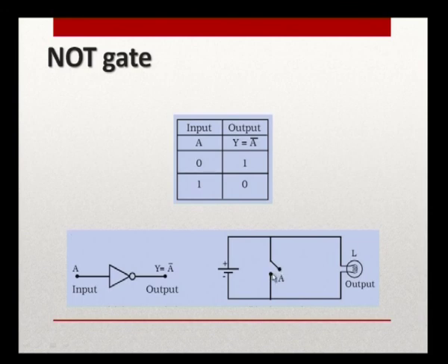When we switch on the switch, when we bring it to the on condition, the entire current is likely to flow through the switch only. The current will not flow through the lamp, which offers some resistance. So, no current flows through the lamp, the current takes the easy path, and the lamp will not glow, so it is in the off state. When the switch is in the on state, the bulb is in the off state. So, this easily explains the NOT operation here.